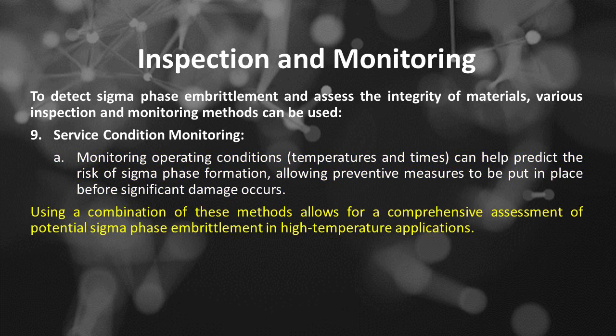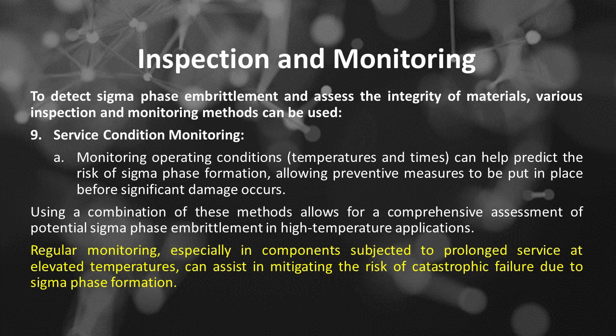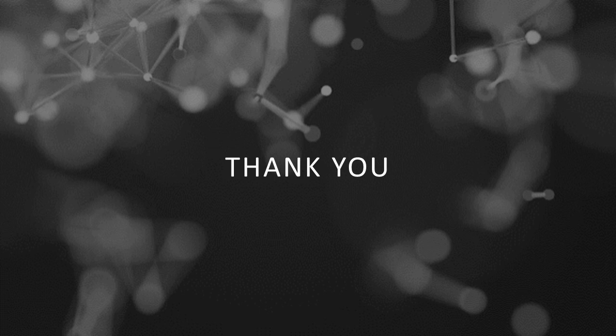Using a combination of these methods allows for a comprehensive assessment of potential sigma phase embrittlement in high-temperature applications. Regular monitoring, especially in components subjected to prolonged service at elevated temperatures, can assist in mitigating the risk of catastrophic failure due to sigma phase formation.